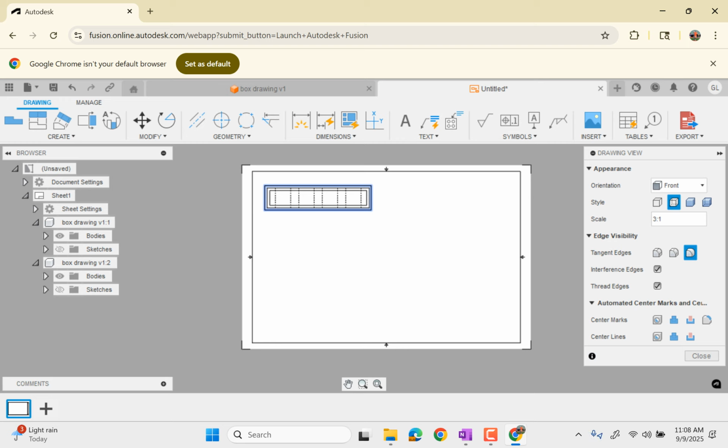If you want to change the style of the picture, over here, you can change it to only the visible edges show up, or hidden edges show up as dotted lines, which is what I find the most useful, or a shaded three-dimensional view. So you have a few choices, but I'm using visible and hidden edges.